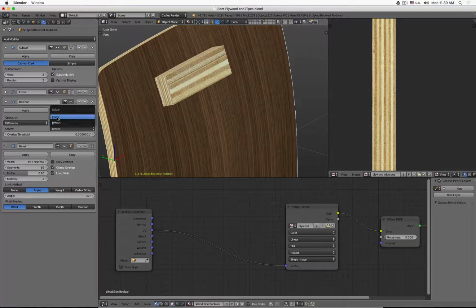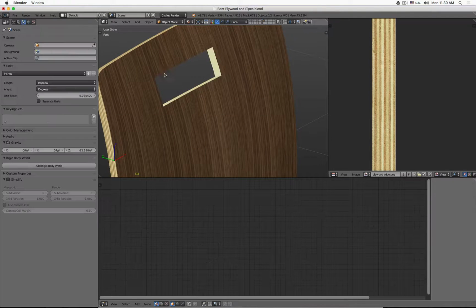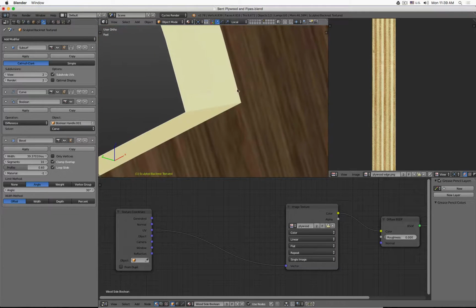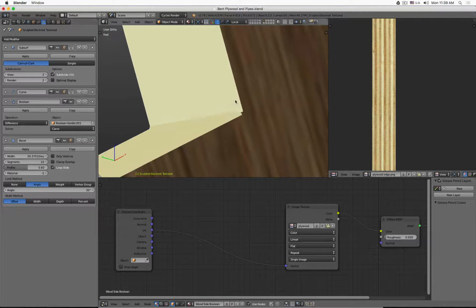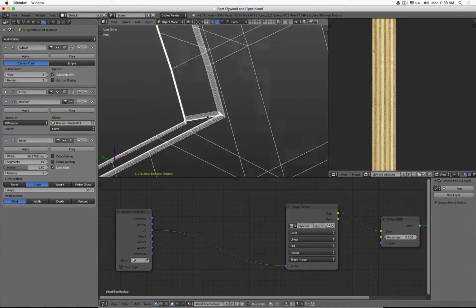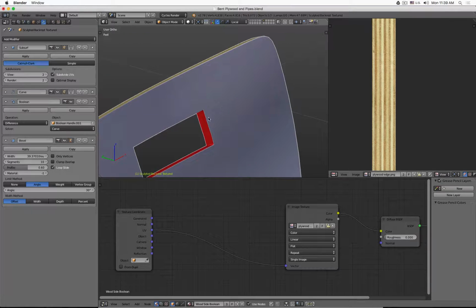This one I will also set to carve, and the bevel modifier, the clamp, I will turn off. But before I turn the clamp off, what I want to show you is there is a bevel now. So with this one turned off, it rounds actually the inner and outer edges evenly. So there and there.